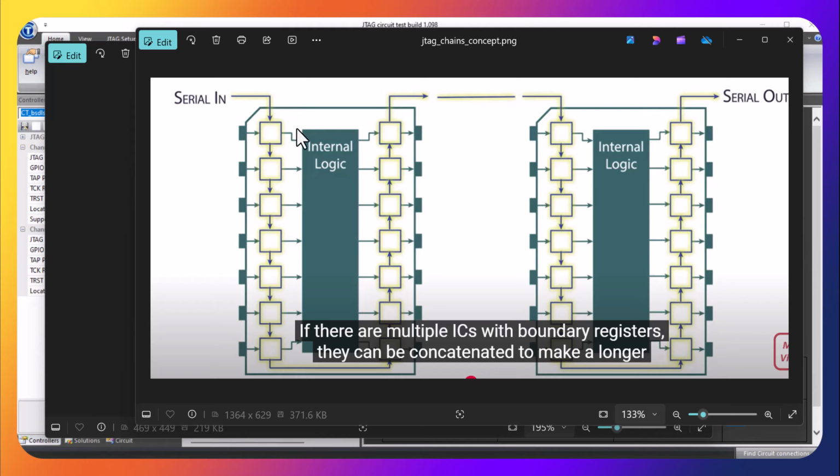In particular, if you look at the implementation on a board, there's a JTAG cell, a boundary scan cell circuit that lies between each physical pin on a board and the internal logic. So when the board is normally running, these cells are in effect transparent. So signals can come in from a pin right through the cell and into the internal logic and back and forth.